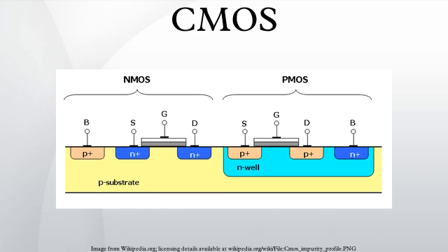Single electron CMOS transistors: ultra-small CMOS transistors achieve the single electron limit when operated at cryogenic temperature over a range of -269 degrees Celsius to about -258 degrees Celsius. The transistor displays Coulomb blockade due to progressive charging of electrons one by one. The number of electrons confined in the channel is driven by the gate voltage, starting from an occupation of 0 electrons, and it can be set to 1 or many.